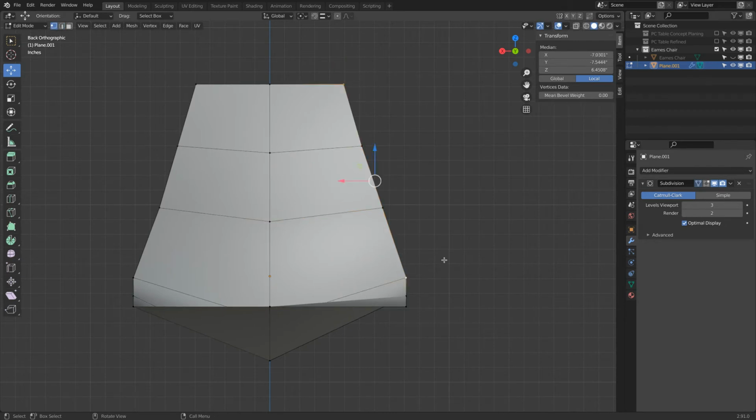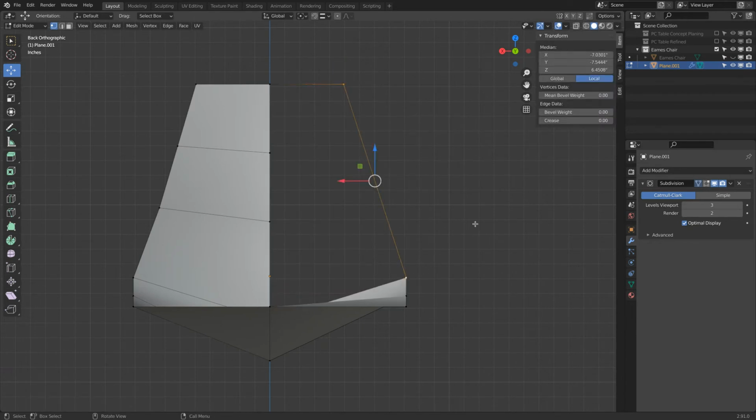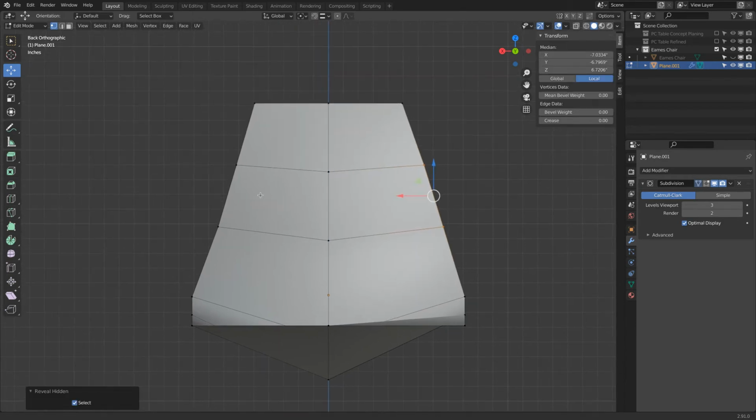But, so what about here, F? You see now there are more. So we can do the same here one more time. We move everything along the x-axis, hold the control key and snap to the edge, hide this, and then here this edge we drew, delete, Alt H, there we are.